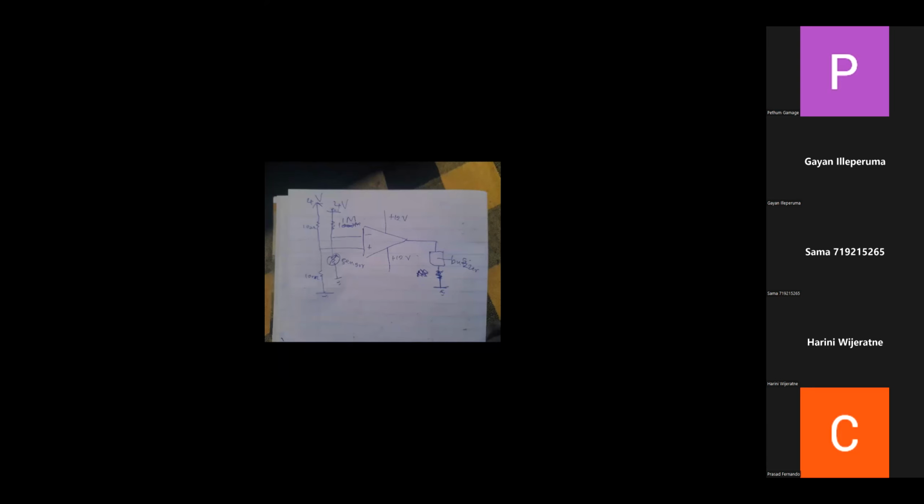Okay, your one is also quite similar. Only thing is now you have put a pull-up resistor. Okay, no problem. Even without the pull-up, it will work. The reason to put a pull-up is when it is floating. Floating means it is not connected to anything. But here, even without the pull-up, you have it connected to the sensor, so it won't be a big issue.